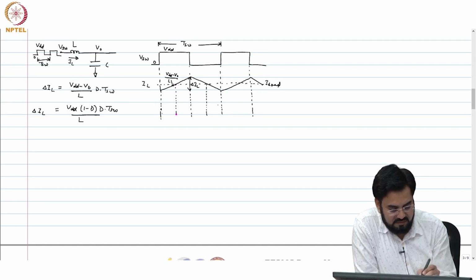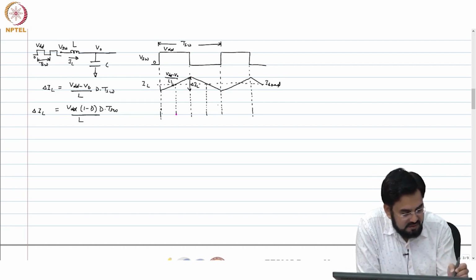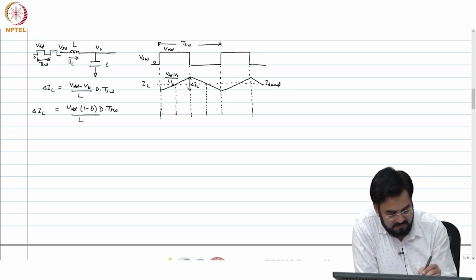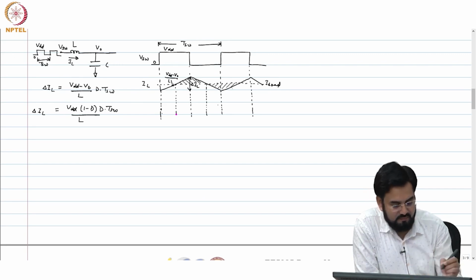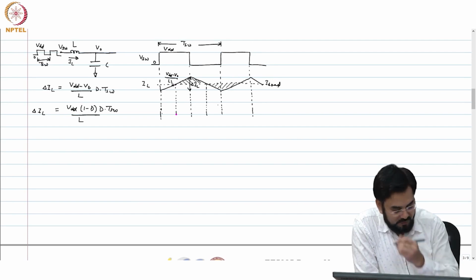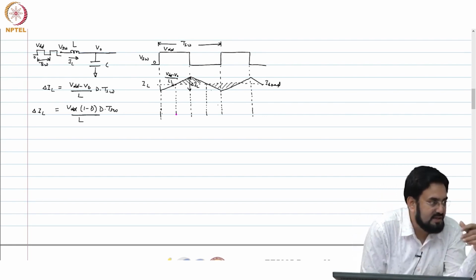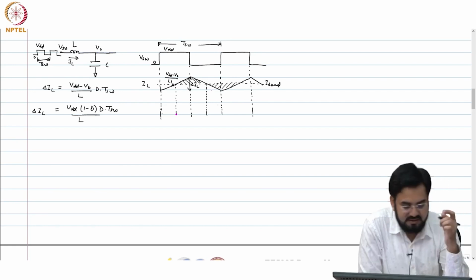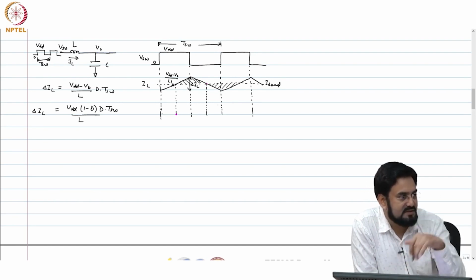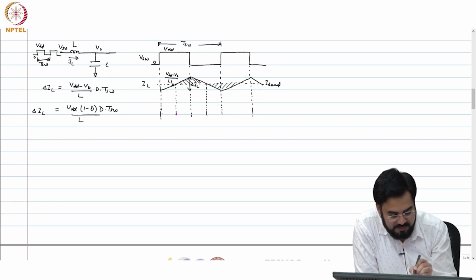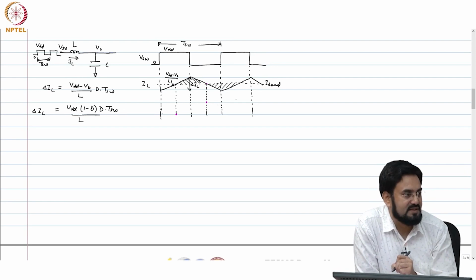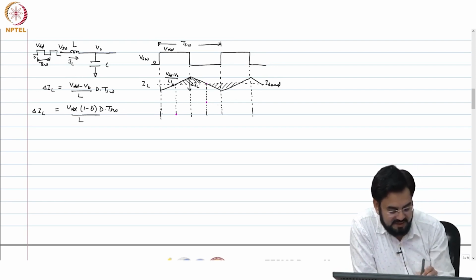And now, let me take some light color, gray. If you look at this shaded curve, which is above your I load, the average current is positive. So the capacitor will keep charging until this point, where the current again becomes negative, which means your peak will be reaching here, and then it will start discharging again. Even if you integrate it, your shape will look like this, correct.